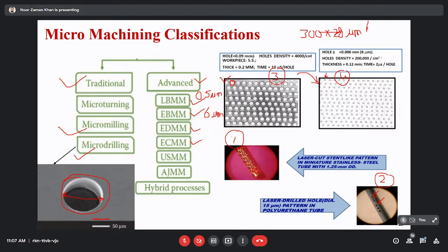A variety of metals and alloys, including conducting ceramics, can be machined by electrochemical micromachining process. So there is some limitation that the material should be electrically conductive, but a new process has been developed, which is termed as electrochemical spark machining. This process is developed for machining ceramics.